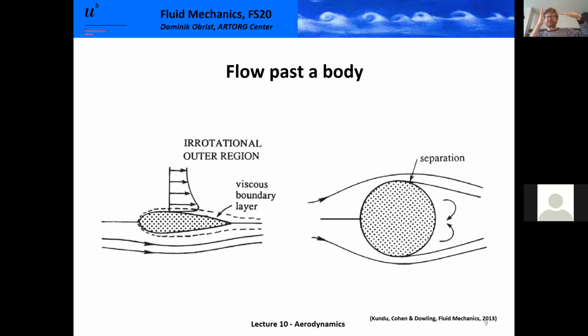And Bernoulli's law, you remember Bernoulli's law, something we did quite early, I think third or fourth lecture. Bernoulli's law tells us that at a stagnation point, all the kinetic energy from the oncoming flow is transferred into an increased pressure. So we have here a peak pressure at this stagnation point, which is equal to 1/2 rho u squared. And that's one of the primary results of Bernoulli's law. So the pressures here at the leading edge of this object are quite high, and they're pushing into the object.